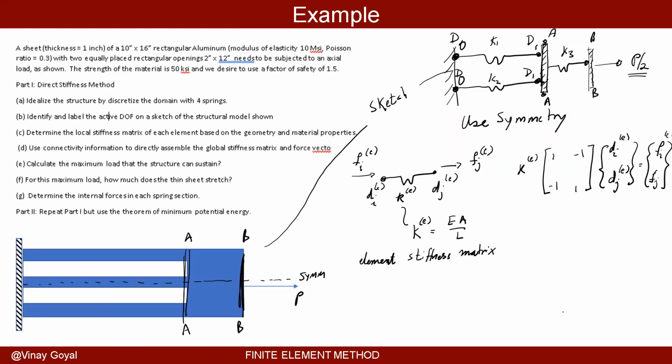If it does not happen, we have a discontinuity in the displacement, which physically is not possible for the structure, right? So we need to guarantee that. All right. So the last active node is the node J for K3. So actually, we are solving for two displacements in this problem, because for D naught, we know that displacement is 0. What we don't know at D naught is the reaction, right?